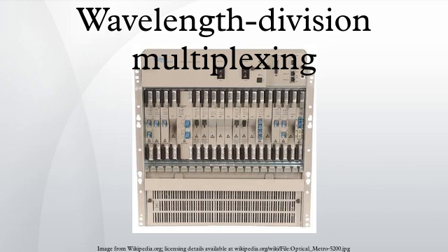The introduction of the ITU-T G.694.1 frequency grid in 2002 has made it easier to integrate WDM with older but more standard SONET/SDH systems. WDM wavelengths are positioned in a grid having exactly 100 GHz spacing in optical frequency, with a reference frequency fixed at 193.10 THz. The main grid is placed inside the optical fiber amplifier bandwidth, but can be extended to wider bandwidths. Today's DWDM systems use 50 GHz or even 25 GHz channel spacing for up to 160 channel operation.